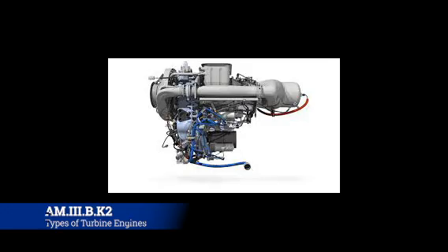And so it's very similar to a turboprop that's doing effectively the same thing, but it's set up so that it can turn a shaft that can turn in both directions, so it can turn both the tail rotor and the main rotor of the transmission and all other good stuff. And so that's technically a fifth type of turbine engine, even though it's very similar to a turboprop, just redirected the power in different ways.